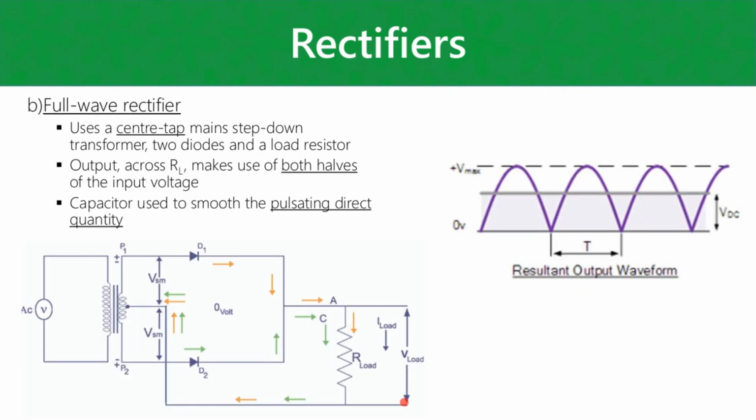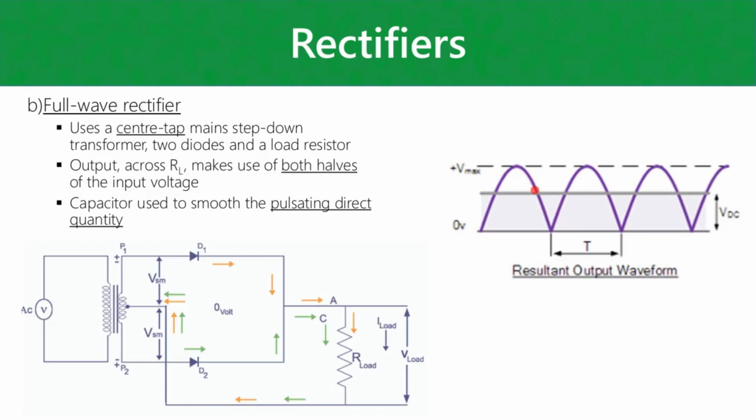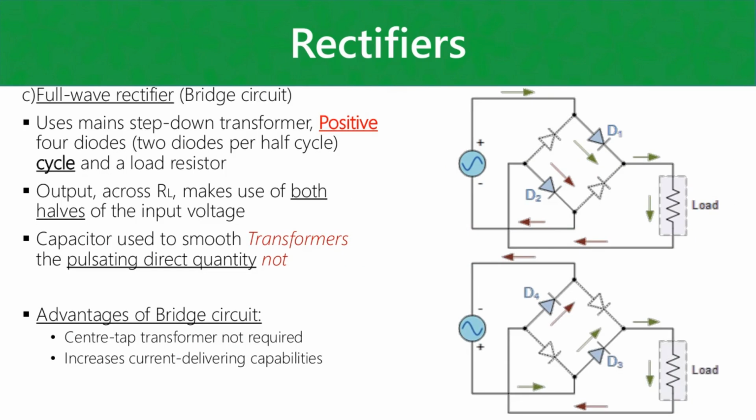But the gist of this, basically, is that you need to know with a half-wave rectifier, you're only rectifying half of your input waveform, or of your supply waveform. So essentially, you're going to have half the RMS voltage on the output than what you're going to have with a full-wave rectifier. Or you're going to have half the average voltage. That's also a valid statement. So that is without having capacitor and inductor filters in the circuit.